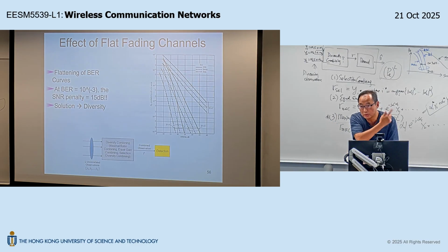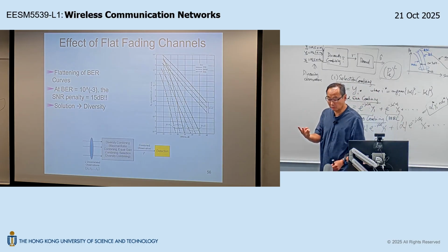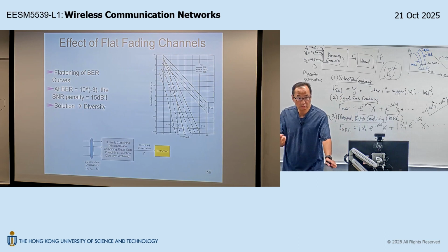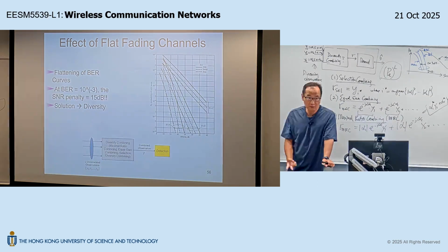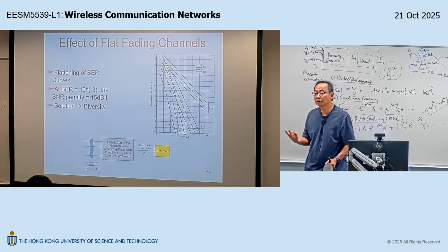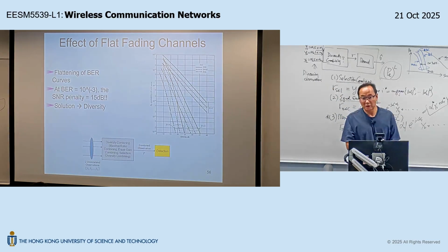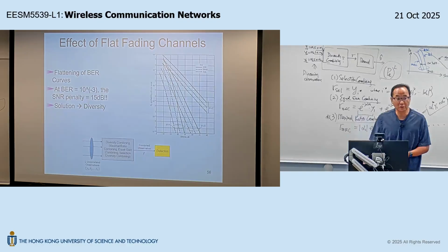And then you go through all these options. You figure out, okay, receive spatial diversity would be an attractive choice, right? Because receive spatial diversity can achieve 2-order diversity without any throughput penalty. And it is transparent to the transmitter. That means you don't need to change the standard to adopt this solution, right? So therefore, you decide to go for receive spatial diversity.